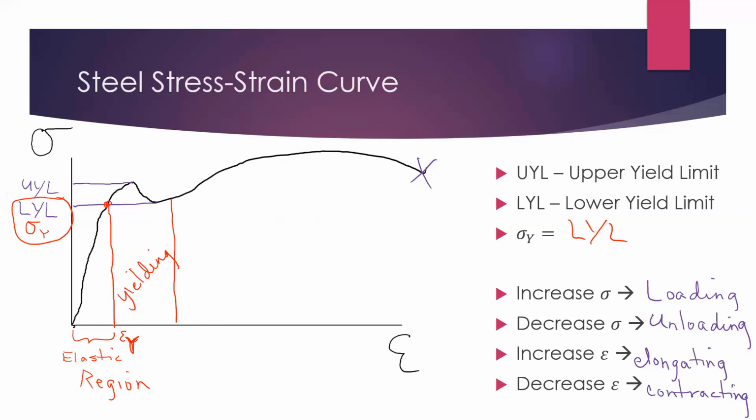In the beginning, the slope is quite steep: you have an increase in your load and only a very slight increase in your displacement. Once you reach yielding, it starts to be more deformation, and some of that deformation is going to be permanent. That characterizes yielding. With that yielding region, would that rightmost line be at that dip? Yeah, roughly, yes, it is at the dip.